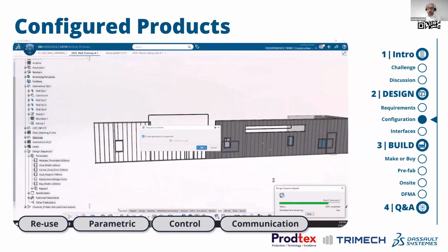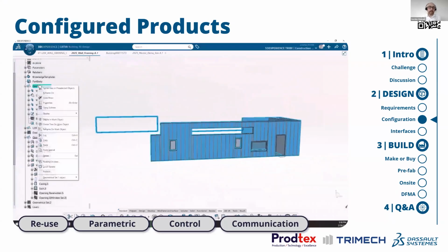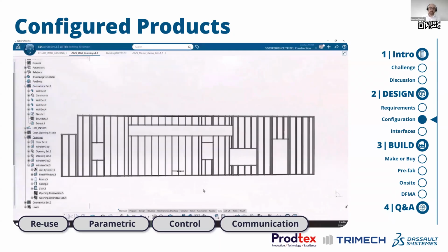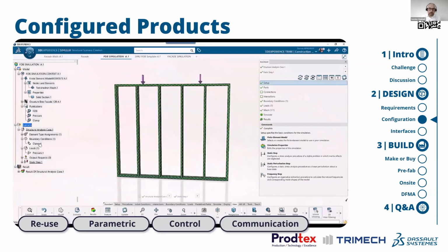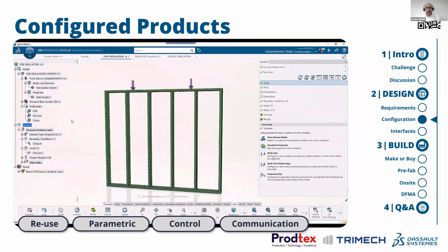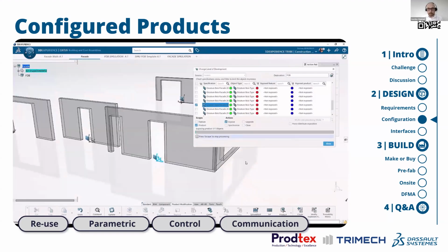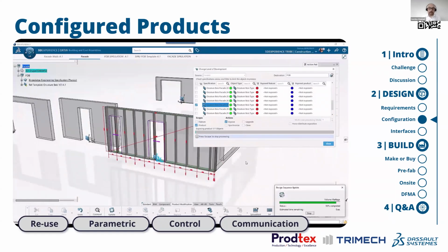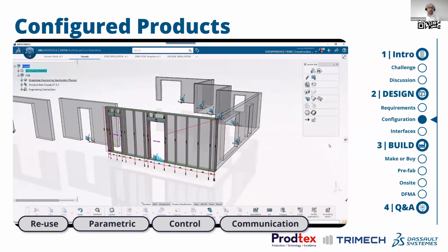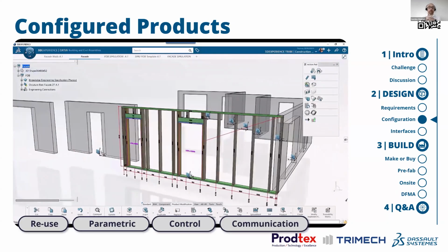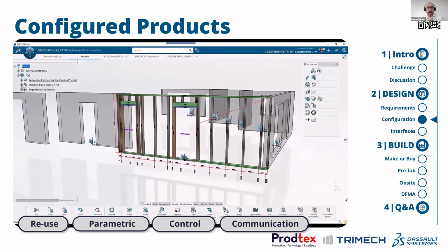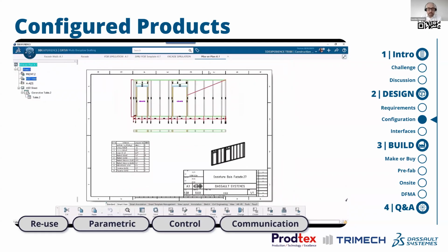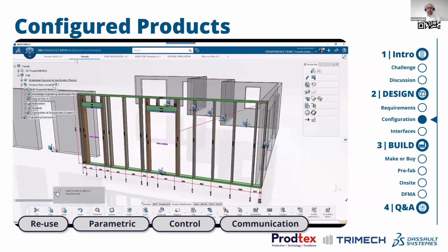Now, beyond that, because we're dealing in this fully connected system, we can also look at things like the strength. So here we have a very simple wall, and we apply a simple load case to it. Now that could be for shipping or handling or lifting into place. Then we place our template wall into our building, add the necessary openings, and that analytical model in Simulia, we can then just tie that into this new wall.